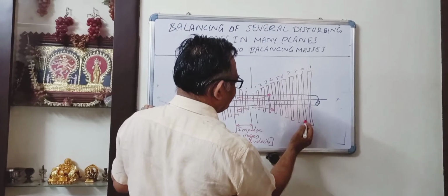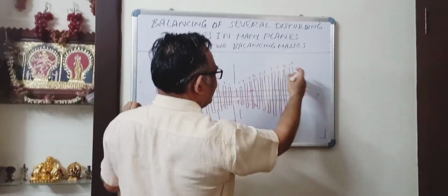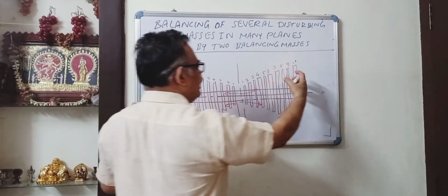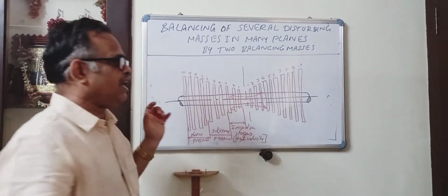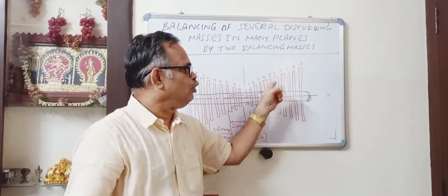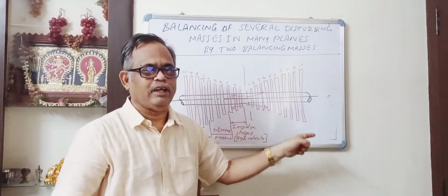Here, why is it called low pressure? Because this end will be connected to the condenser, where there will be a vacuum pump trying to pull the steam. So here low pressure will be there, right?